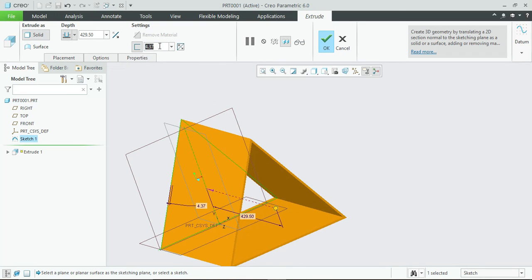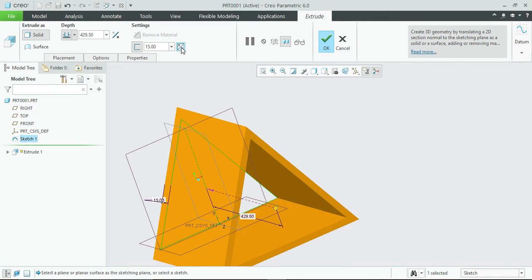Okay, so after that, in the solid you can add a thickness, hollow with thickness. See, here you can add thickness internally and externally. You can just adjust it.